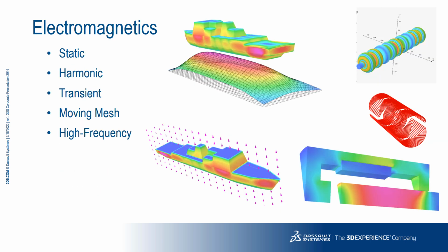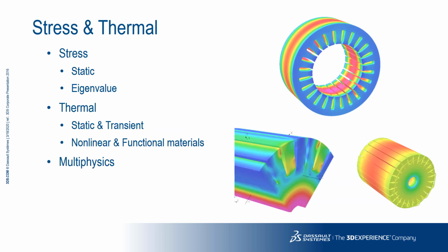Taking a look through the solution capabilities now, Opera started with a low-frequency electromagnetic solver. It's been used in many industries around the world to deliver accurate simulation results in computationally efficient timescales. It includes capabilities for ensuring high accuracy results from simplified methods, such as thin plate elements for ease of use of high aspect structures, such as magnetic shielding or ship's hulls. Besides electromagnetics, Opera 3D can solve thermal and stress problems to allow for full multi-physics solutions.